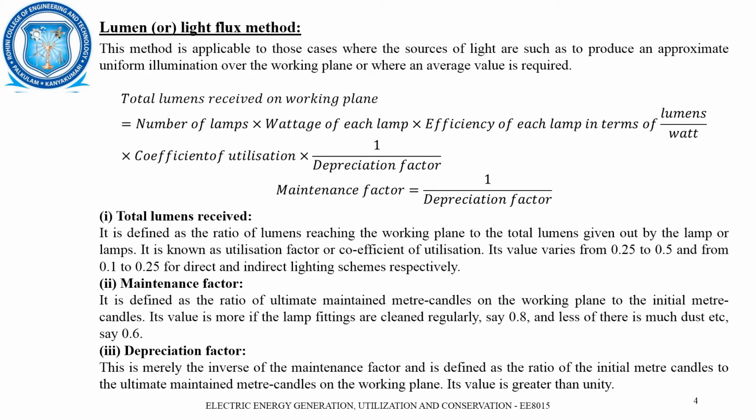While considering the lumen or light flux method, we have to calculate the total lumens received on the working plane. This can be achieved with certain factors like how many lamps are used, what is the wattage level of each lamp, how the efficiency of each lamp is represented in terms of lumens per watt, what is the coefficient of utilization, and also the depreciation factor. Either the depreciation factor or the maintenance factor can be considered.